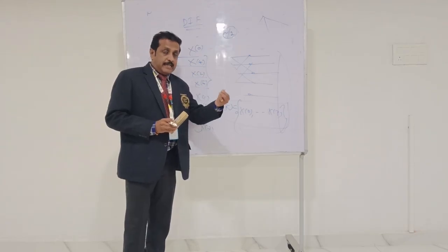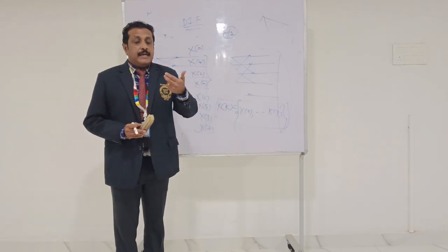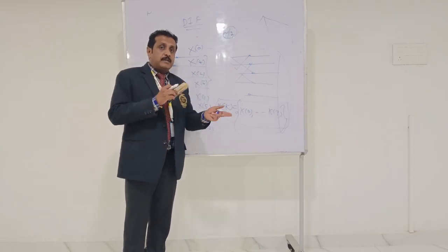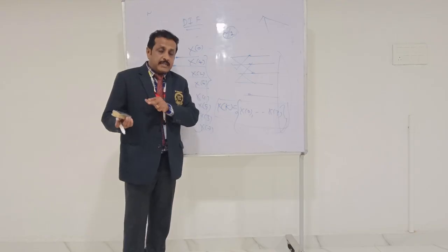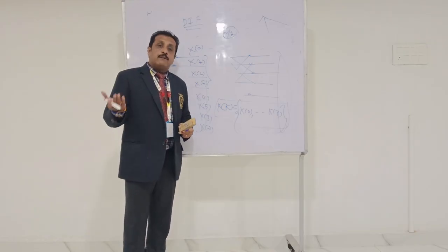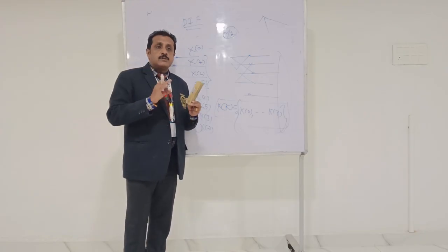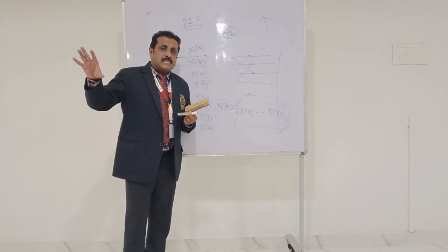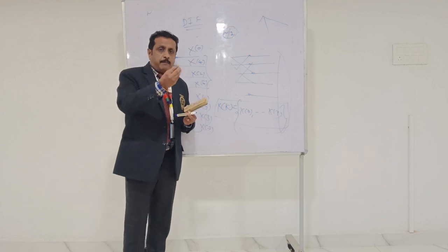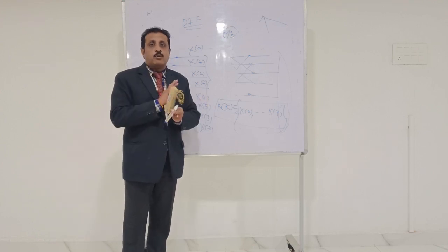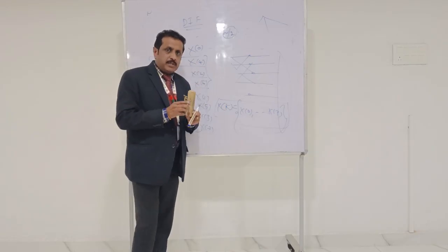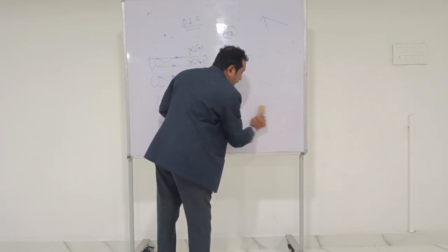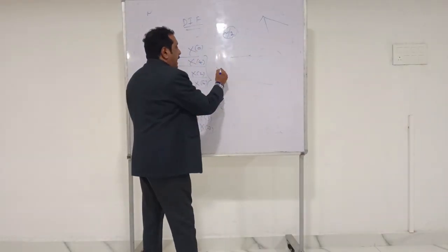So in DIT it is 2 point, 4 point, 8 point. In DIF it is 8, 4, 2. In the same way the butterflies come in reverse order. So in the second stage you get the butterfly in DIT, and in DIF you get the butterfly in the first stage. So there will be some slight changes, but the final answer of both approaches, DIT and DIF, will be the same. So once you have completed your computation, you will get the final DFT answer.